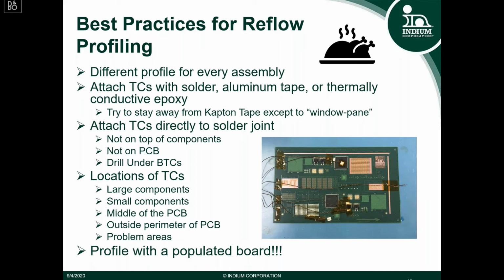I've actually run a DOE where one thermocouple was attached to the top of a component and another was soldered under the bottom of the component. There was a 10-degree difference between the two readings. So it's important to make sure that the thermocouples are attached to the solder joint.